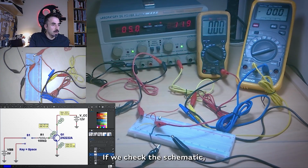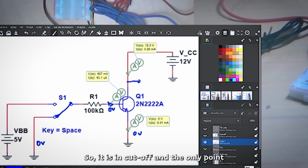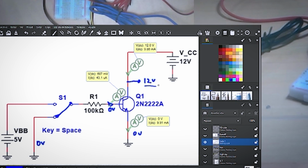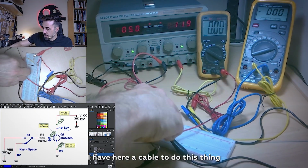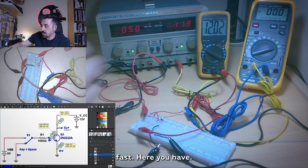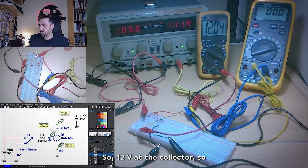If we check the schematic, we are going to realize that we have right now a connection between this point and this other. So 0 volt here, consequently 0 volt here, 0 volt also, so no current through the base. So it is in cut-off, and the only point is to verify that at the collector you have 12 volt. Let's go to measure that. So I have here a cable to do this thing fast. Here you have, so 12 volt at the collector.